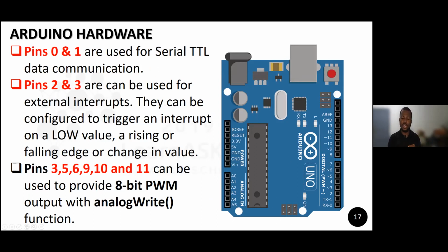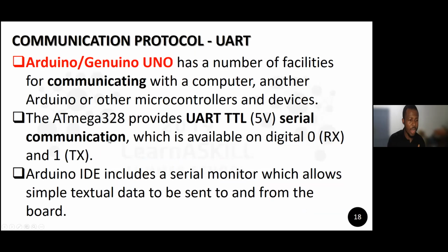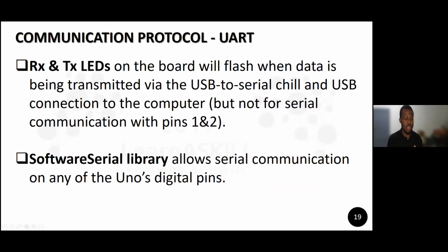However, if you use the ICSP header, you can't have serial communication, as in you cannot have Serial.println between your computer and the Arduino. If you want that, you would have to use the USB. That is the reason you don't want to connect these pins. Sometimes if you connect just one of them, your system may work, but just avoid any hassle and avoid using these two pins. That's all. If somebody has any question, you can always draw my attention.